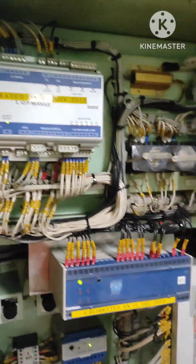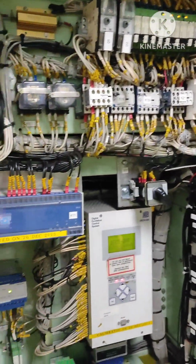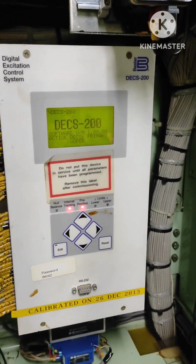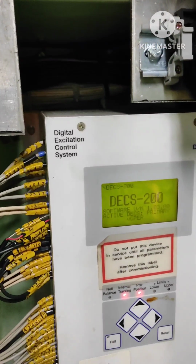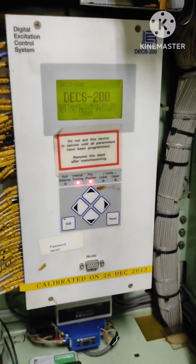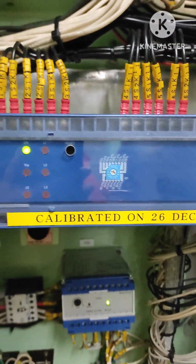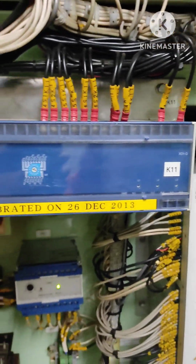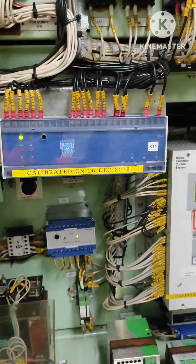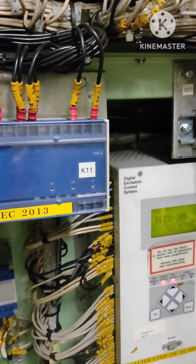This panel I have opened just to show the internal components of DG3, and as I said, it is similar for the others. So this is one component, DEX, that is digital excitation control system. This is like a kind of AVR, which is for regulating the voltage of the generator. This is a differential relay, which is specially fitted to protect the alternators from any internal faults that may develop.